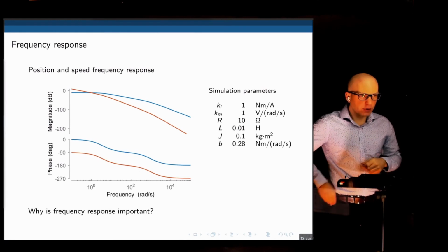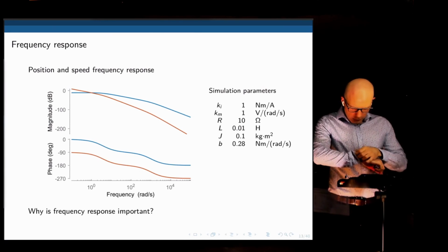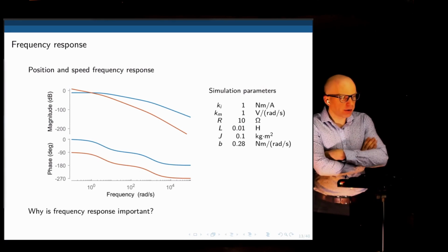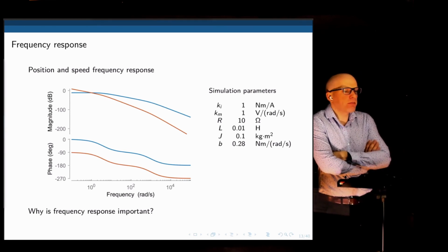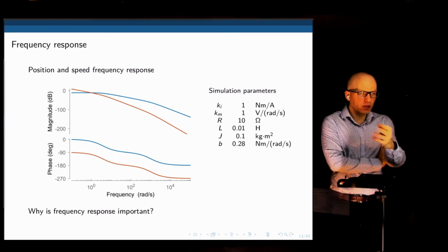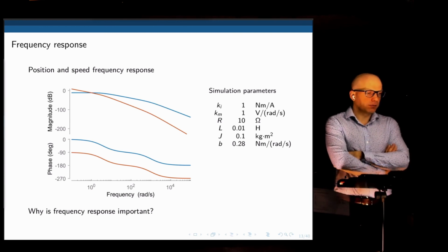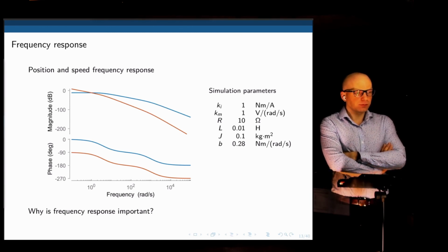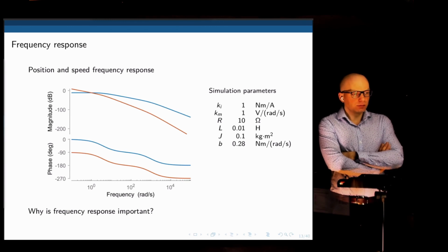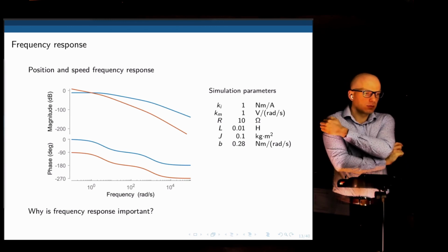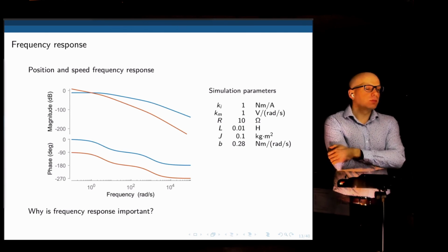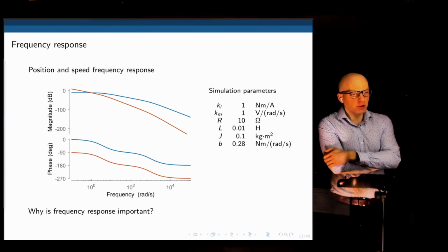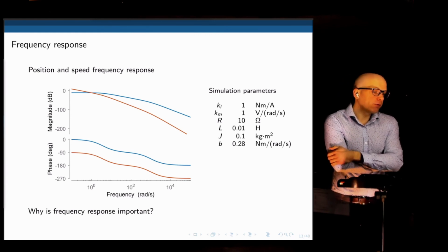Now let's look at a frequency response. Before we look at frequency response, why do we care about frequency response when you design something? What is the actual meaning of frequency response and what information can you take from this Bode plot? You can find out what the actual transfer function is based on the different places where there's the rises and falls and such, and the phase shifts and stuff. Exactly. That's one application. We can indeed infer the transfer function parameters and the shape of the transfer function itself